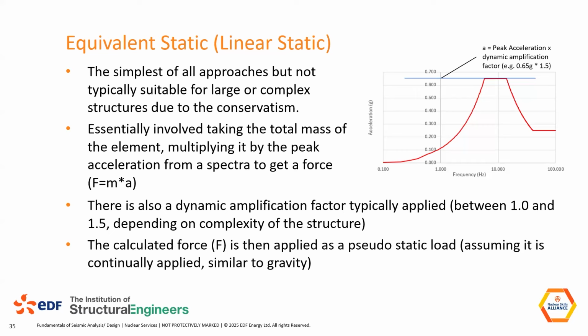But without splitting them up, in equivalent static, we're trying to do something very simple. It's basically a hand calc. We don't know what accelerations apply, but we know that no accelerations will be greater than this 0.65. So we take 100% of the mass times the peak response, and we apply that as a static force. It is that simple. There is also a dynamic amplification factor you'll see in codes.